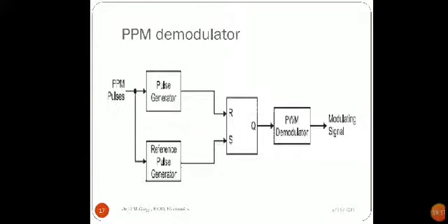The advantages of PPM are again the same as PWM. The important point is that the width and the amplitude of the pulse position modulated signal is constant, so constant power will be outputted. This is the very important advantage of PPM. The disadvantage is that it needs extra circuitry compared with the PWM. The application includes radio frequency communication, then contactless smart card, high frequency RFID tags, etc.